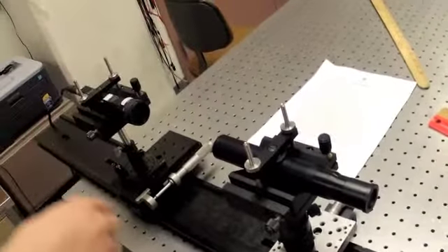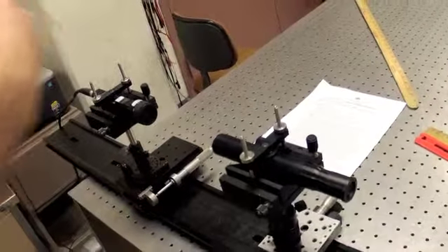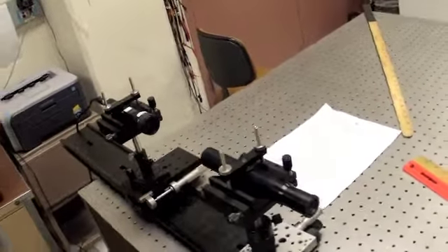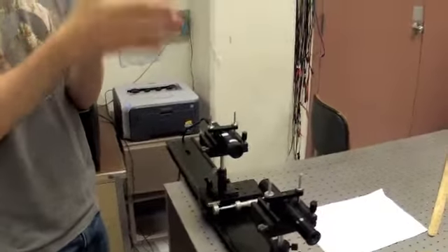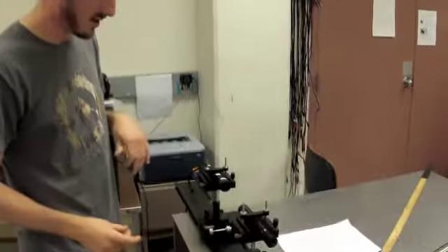In order to start out the lab, we first took off the lens and measured the pixel size, both width and height. To do this, we used the microscope objective to focus on one side of the pixel array, recorded that position, focused on the other, and then subtracted the values to find the pixel width. We did this for width and height.